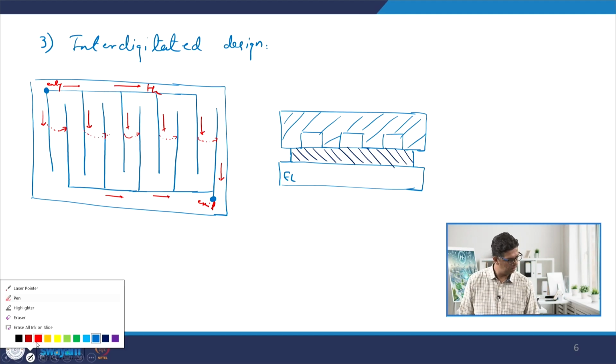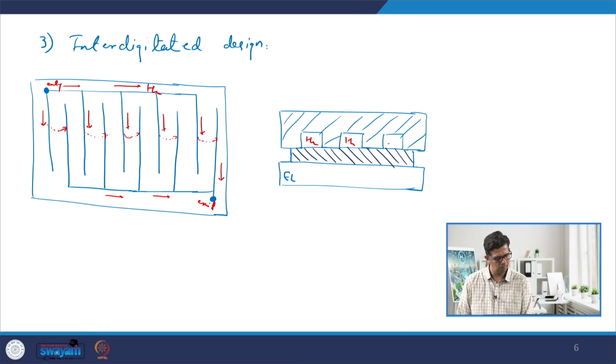So when we have, let's say, hydrogen here flowing through these channels, this hydrogen is forced to flow to the other channel through the diffusion layer, as it has no other way to reach the other channel. As we can see here on the figure on the left, the entry and exit channels are not connected directly. There is a space in between, and since we have inflow, in order to have the exit flow, the hydrogen should flow from inlet channels to the exit channels, and that is the only way possible. This flow of hydrogen should happen through the diffusion layer.